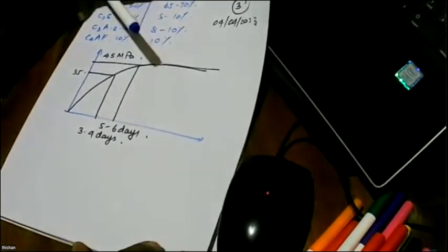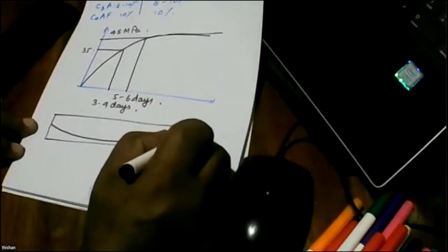The reason is, we are going to use this option where we can cast the beam like this, where we are going to get a curved tendon, and we use this for post-tensioning.